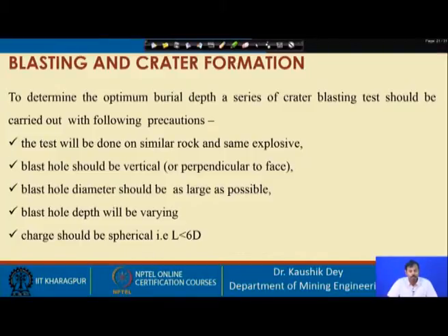The tests must be done on similar rock and with the same explosive, because we want to know the interaction between two things, one explosive and one rock. So, the experimentation must be carried out on similar rock. It is better to use the same bench, and we should not change the explosive during our experimentation.